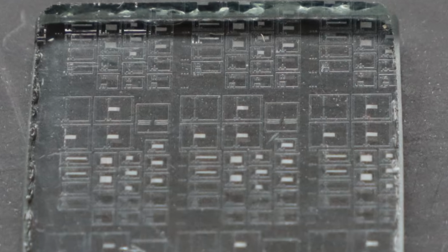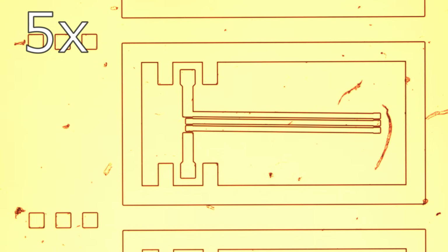Next up is this piece of glass. In a previous video I have etched channels in the surface. Now it's hard to make out any details with the naked eye, but under a standard microscope they look something like this, where these rougher looking areas are the etched parts of the surface. So let's see if we can establish how deep these channels were etched using the CSI.